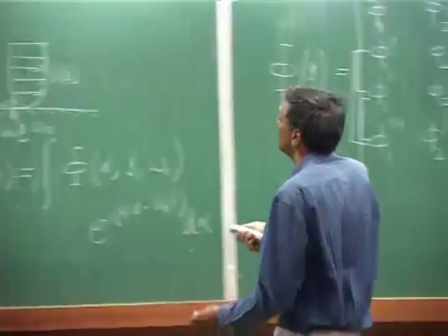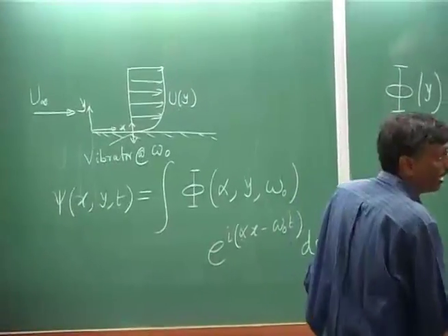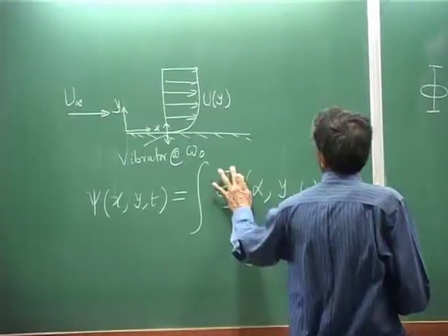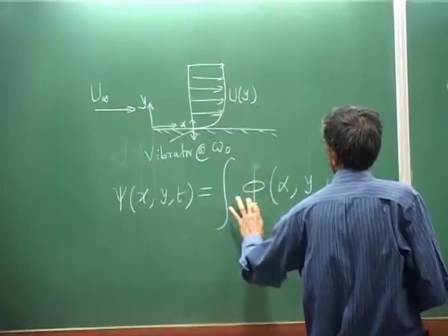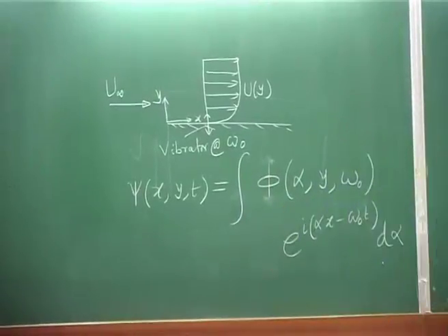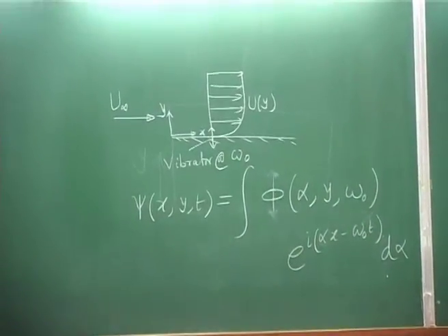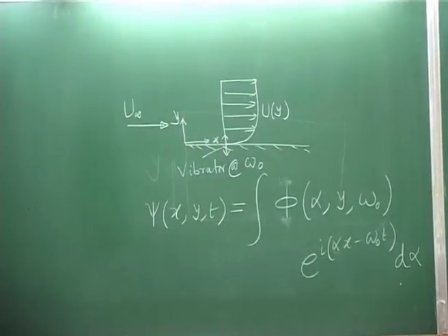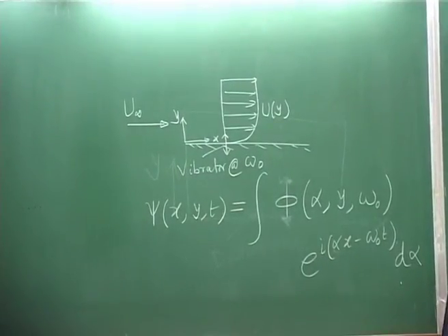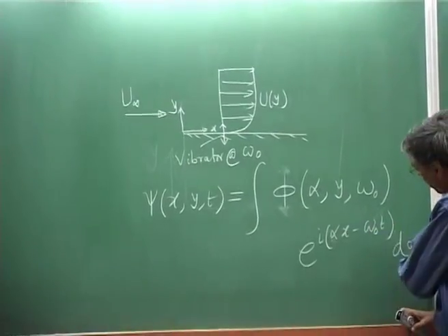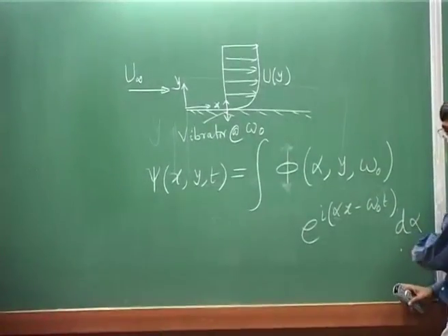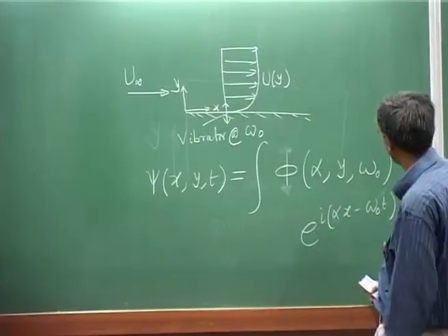That is what you can now see, that phi is that. Well, I think I have used a lowercase phi, so let us keep it lowercase phi, and then what we are going to do is obtain the solution given by that Orr-Sommerfeld equation for all possible values of alpha, and then integrate this.